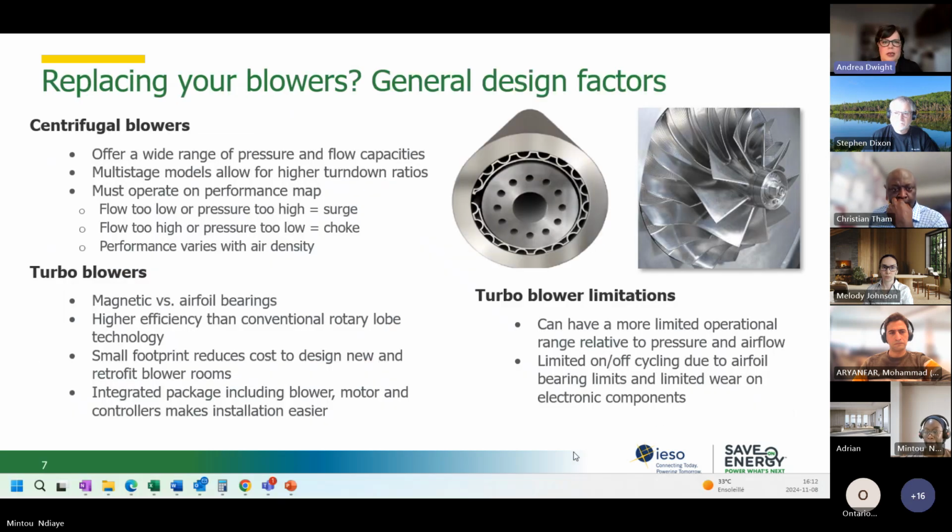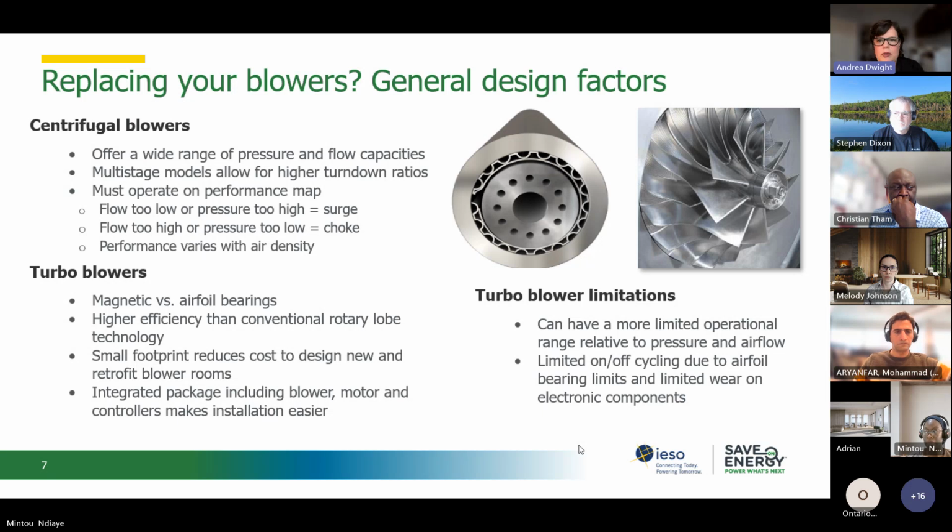If you're replacing your blowers, especially in your bioreactors, you're probably going to be looking at turbo blowers because they're so efficient, but centrifugal blowers still have their place. The centrifugal blowers have a wide range of pressure and flow capacities. They allow for fairly decent turn down ratios and are workhorses, but you have to keep them on their sweet spot on their fan curve. So you have to be aware of that.